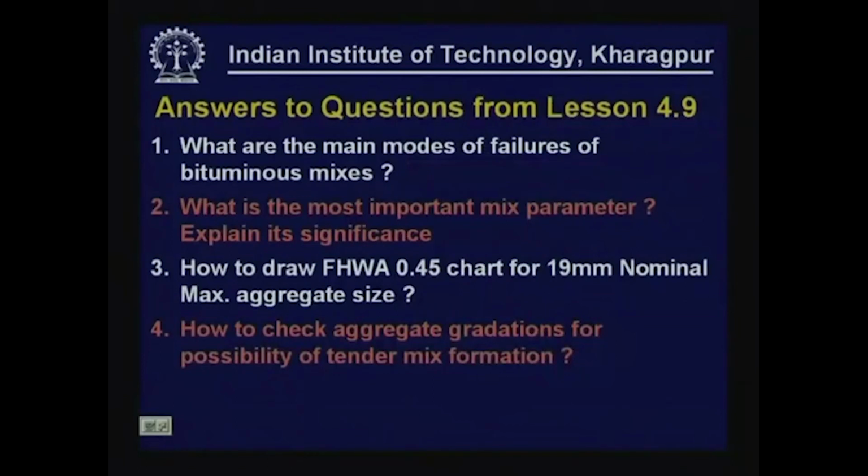But of course, in this lesson we were concerned about the failures that are occurring in the bituminous layer. Other types of failures are bleeding, that is seen on the surface because of the presence of excessive bitumen, because of very little air void that was present, secondary compaction. So, bitumen coming to the top was another failure that we have seen. Similarly, these 3 or 4 types of failures can lead to secondary types of failures also.